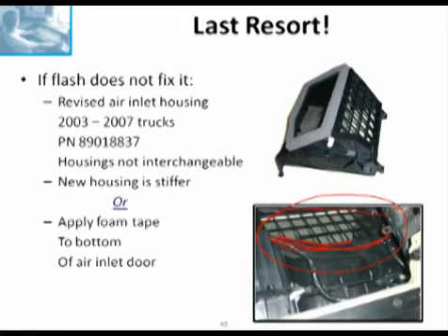So, you know, these are the days where you're going to have an AC complaint and you can fix it with a flash. You can have a vibrating AC belt. You can have a groaning noise coming out of the air conditioner. You can have an engine stalling when you have the AC on, and you can have a whole variety of symptoms for HVAC that you're going to be able to fix by flashing a module in the vehicle to make it program differently.